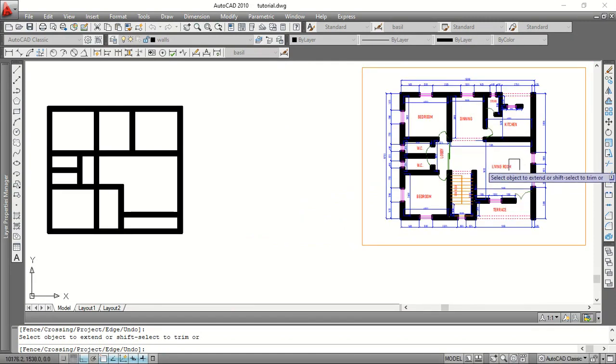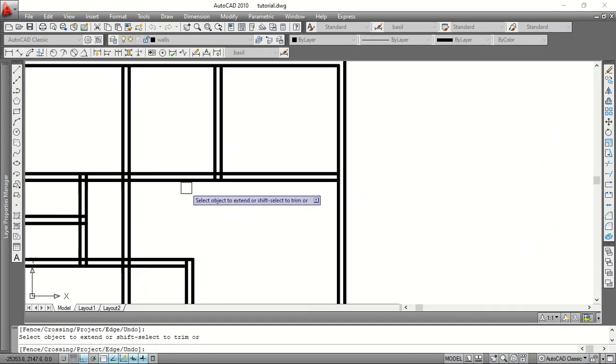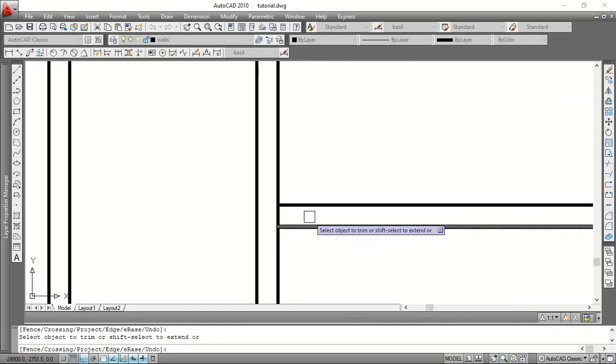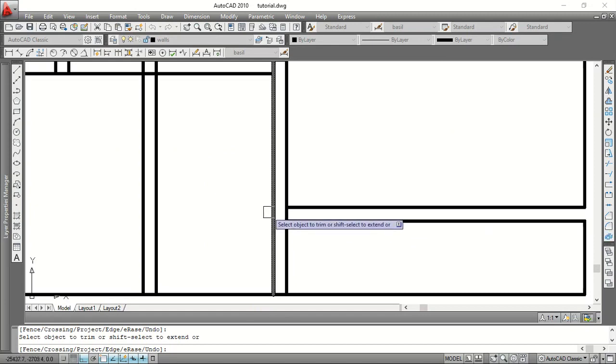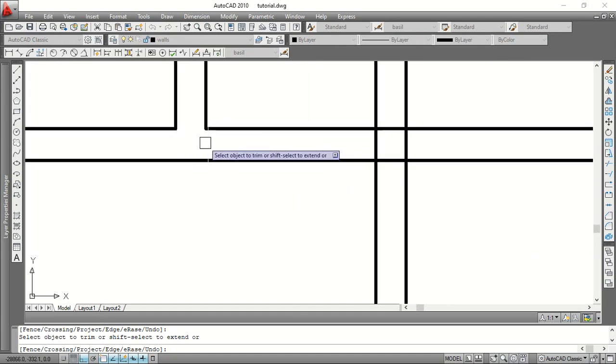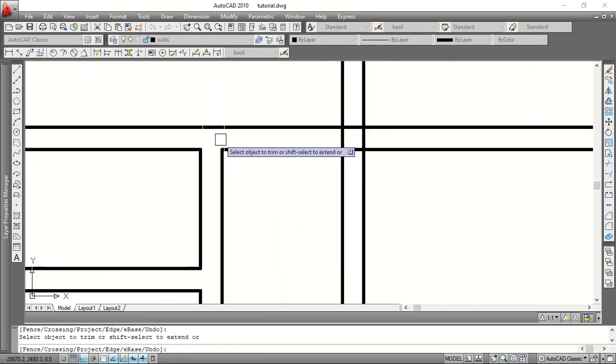Okay. So we are getting there. We are almost there. Just a few minutes. So what we've done is a key thing in this design. We are almost done. So the next thing I want you to do quickly is let's do the trimming. Let's start trimming our walls so it shows continuity, because the moment you leave a wall like this, it means this is a different material from this. Okay, so it's always important to define it properly. So let's just define it first. There are some places we will still close back, but let's just do this first for clarity's sake.